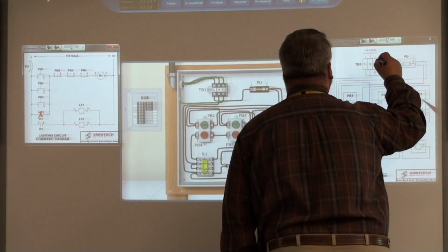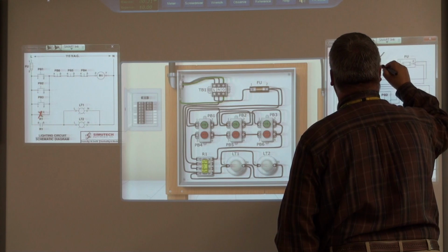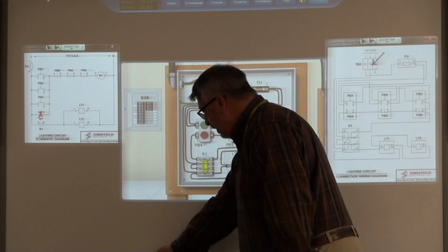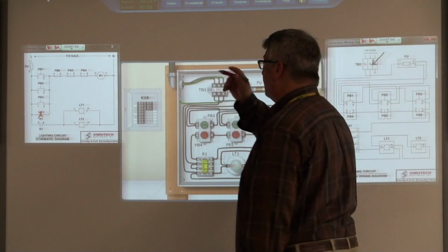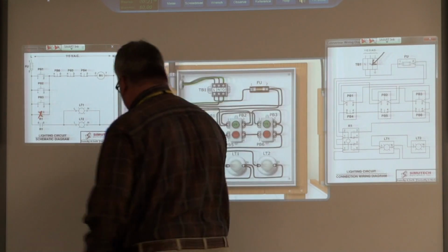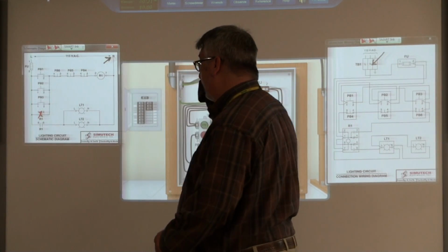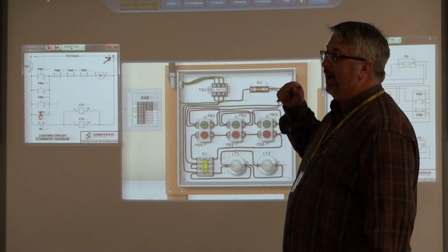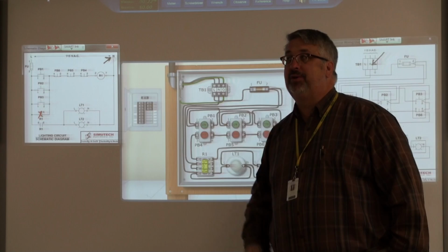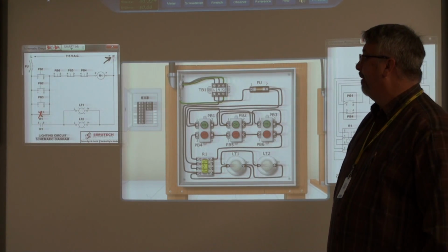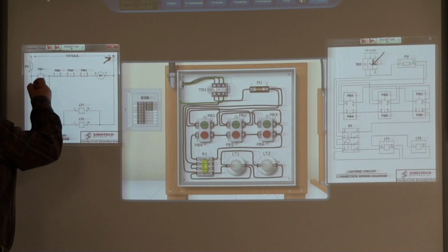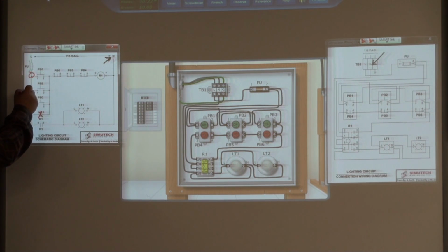We've got our meter here across our neutral or ground. We'll do it over here, it doesn't matter. If we're on neutral, we've got our black lead right there. On this circuit, once we let go of the button, are we going to measure 115 volts all the way down the left side of the schematic? Yep, which is a no-brainer really, because this is connected to line, this is connected to line, and that's connected to line. So that doesn't change anything whatsoever.